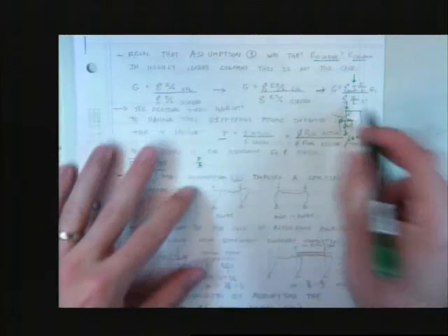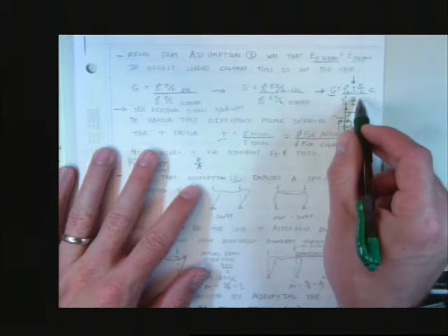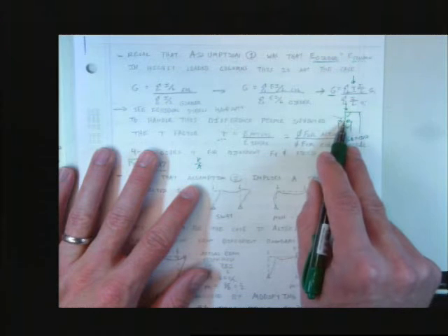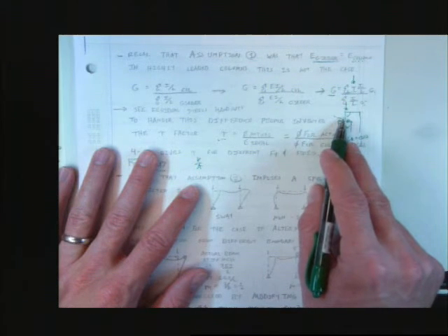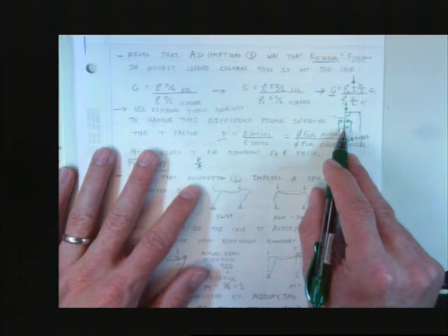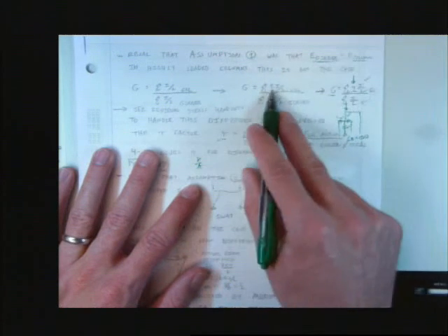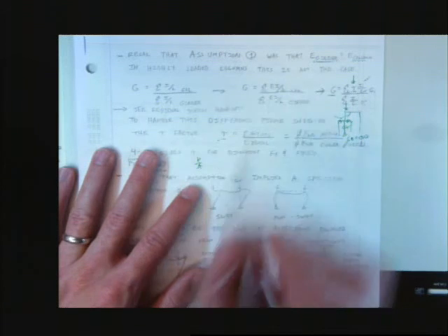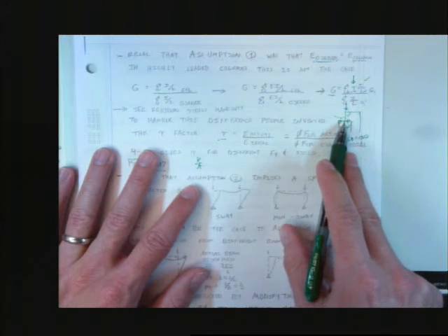All you're doing when you use the tau factor, remember, G is all about accounting for stiffness. It's accounting for the equivalent rotational stiffness at that joint. The tau factor is discounting the contribution of the columns to that stiffness. Remember, I is a stiffness term, L is a stiffness term, and E is a stiffness term. And we're discounting the contribution of the E to the stiffness at that joint from the columns.